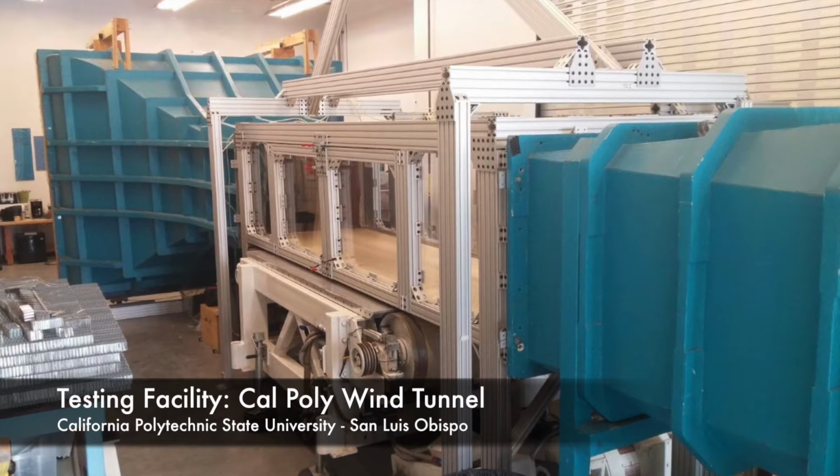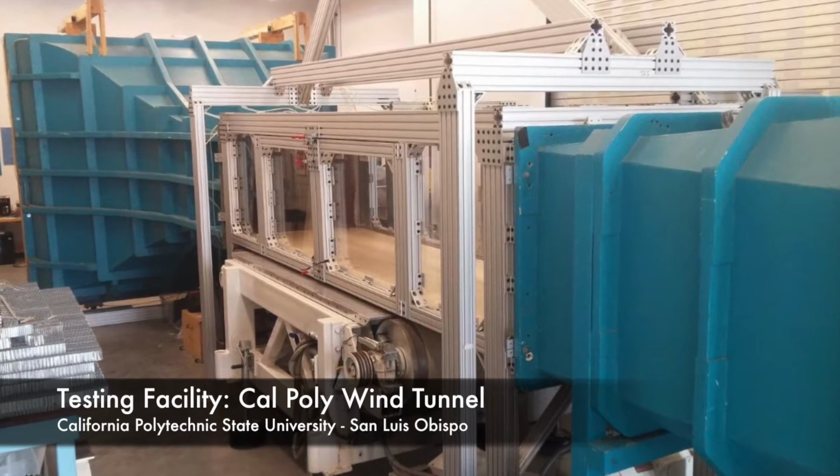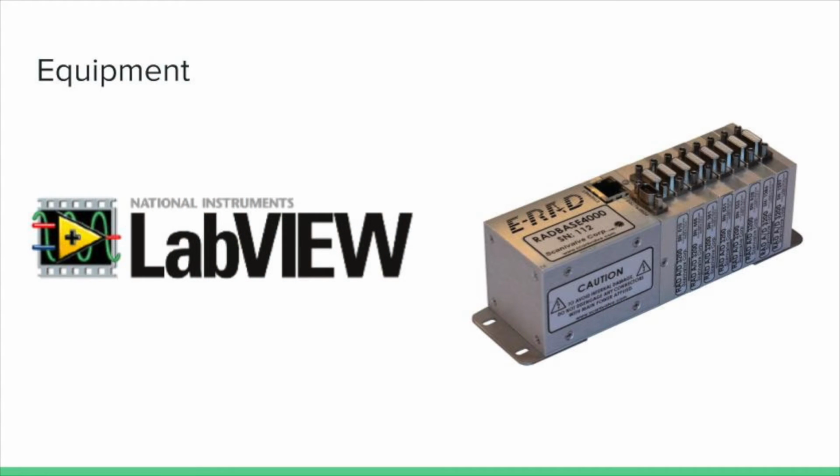The cylinder lab was conducted in Cal Poly's low-speed wind tunnel, which has a top speed of 58 meters per second and a fan with a max RPM of 1200, controlled by the variable frequency drive. Data was collected while the wind tunnel was running using LabVIEW 2015 and scanning valve ERAD 4000.